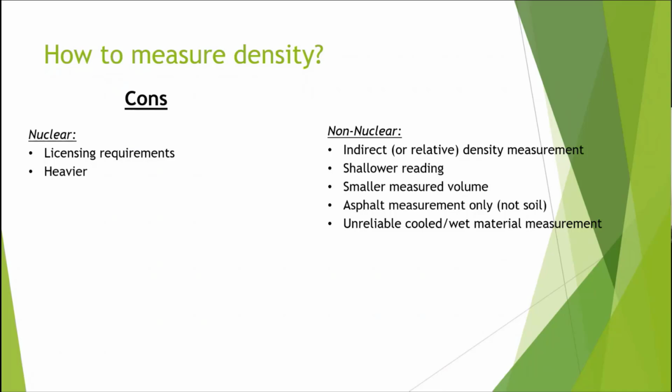And so you might be 6,000 tons down the road, yesterday's paving and half of today's paving, before you get your core results. So that means during the process, you need to be doing some measurement, whether it's using a non-contact gauge, a DPS, or a nuke gauge. If you don't, you're going to get what you get. So that's where the DPS comes in.